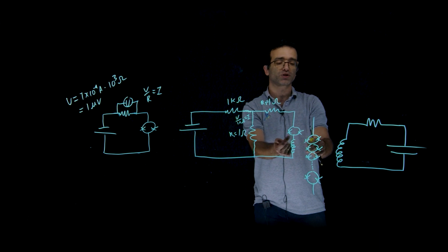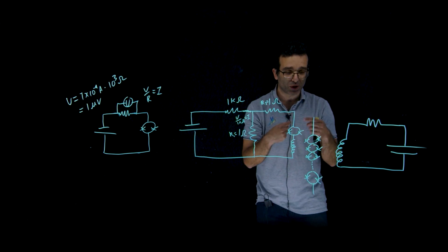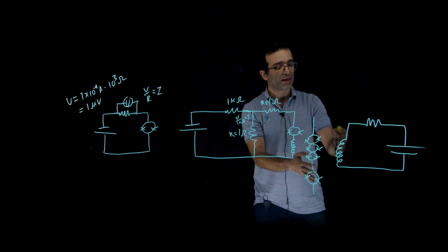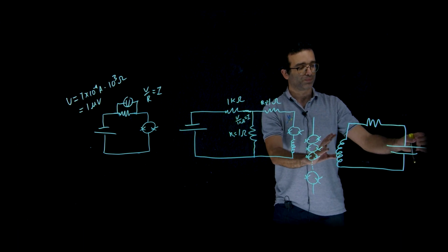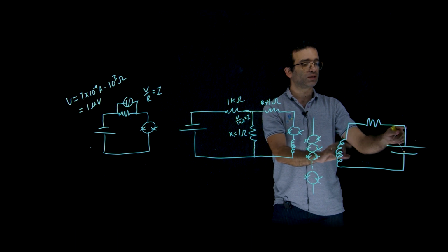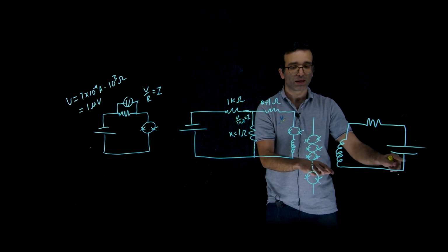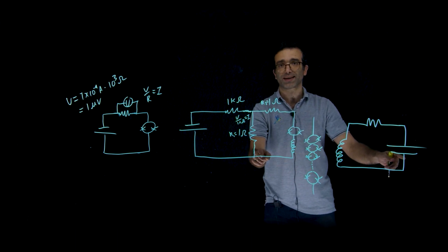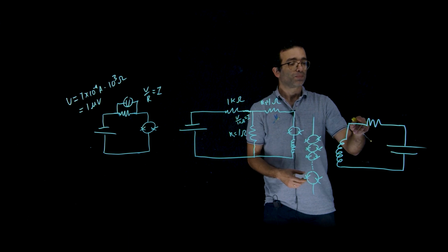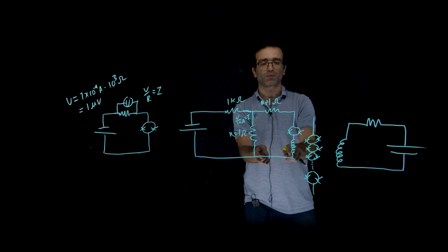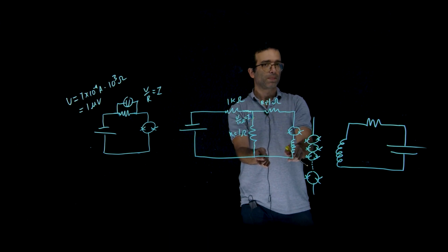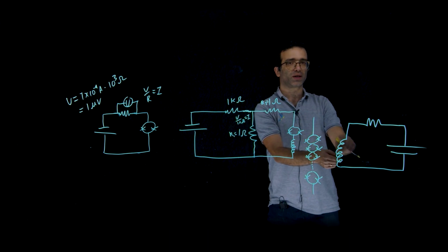So the coil generates a field that generates a flux into the SQUID array. And this is compensated by what is called a feedback coil. Now this feedback coil, if I know the current here, in a way I know what is the current here, right? So in principle, I just moved my problem from here. At the beginning, I wanted to know what is the current here. And now I'm asking the question, what is the current here?